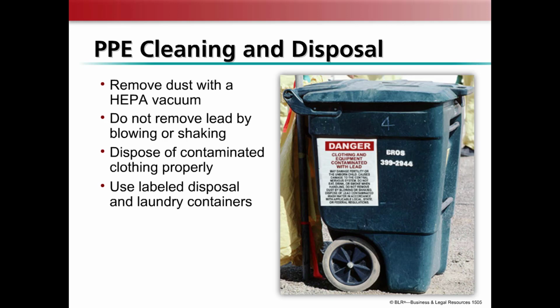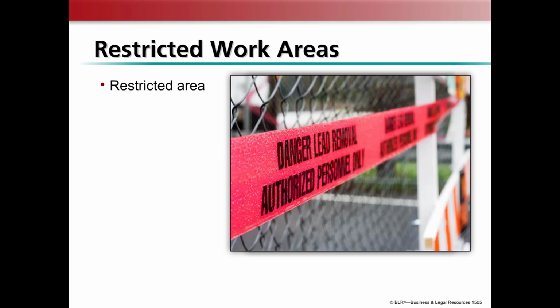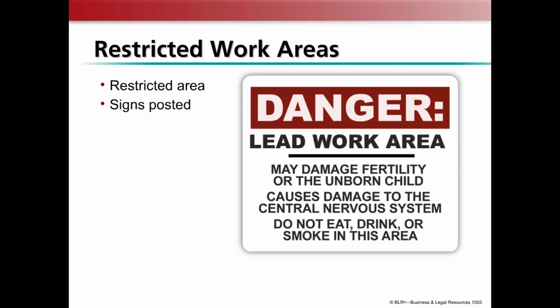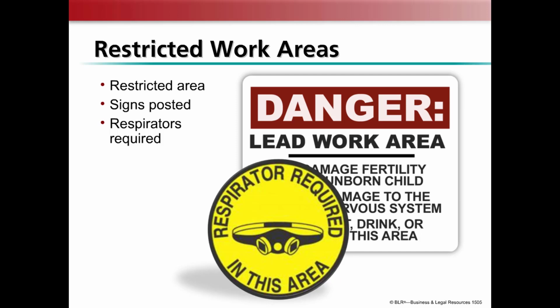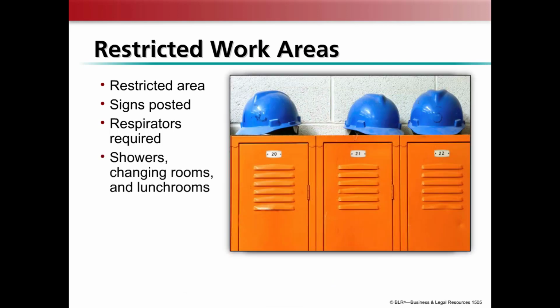Dispose of lead-contaminated wash water in accordance with applicable local, state, or federal regulations. Work areas with lead concentrations greater than 50 micrograms per cubic meter are designated as restricted. Signs are posted stating, "Warning, lead work area, poison, no smoking or eating." If you work in an area with lead concentrations greater than 50 micrograms per cubic meter, you must wear respiratory equipment in order to reduce the exposure below the PEL. Showers, changing rooms, and lunchrooms are provided for workers exposed to airborne lead above the PEL.